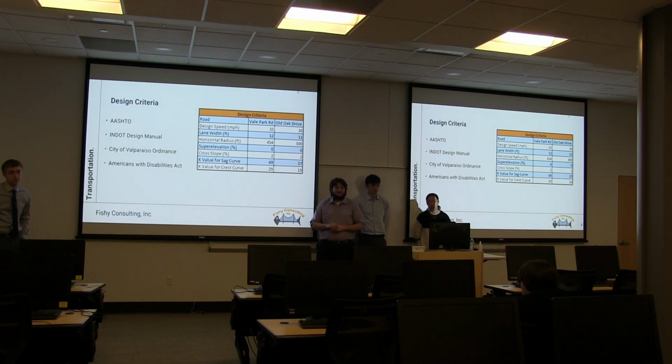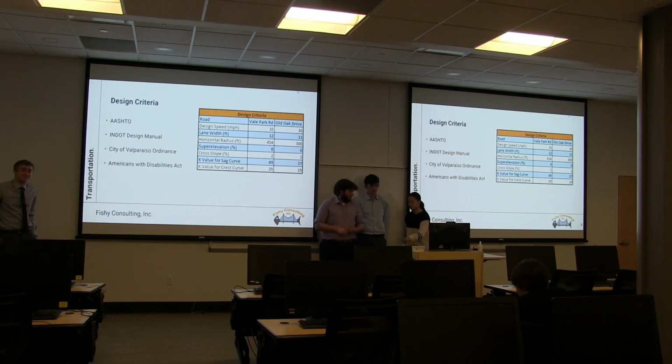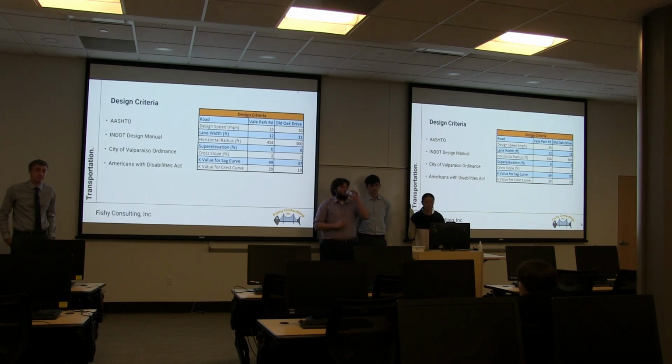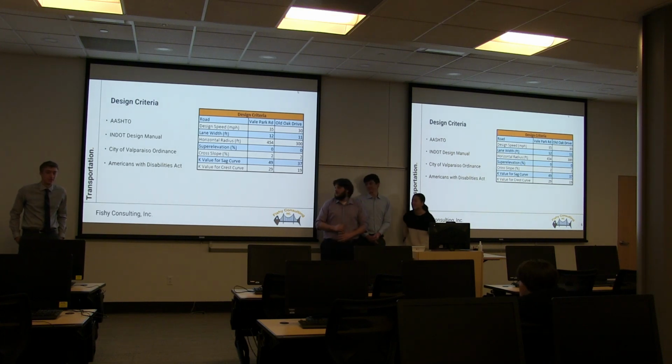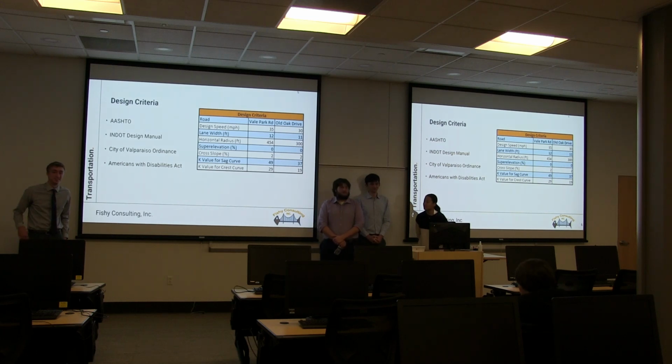I think Hunter wants a simple question for you, because you may open my eyes to a Valpo ordinance. You said that the velocity in the swale is less than 1.9 and the depth of the water is 4 inches. Is that for conveyance or for a BMP, like treatment? If I am using the swale for conveyance, am I sticking to those numbers?